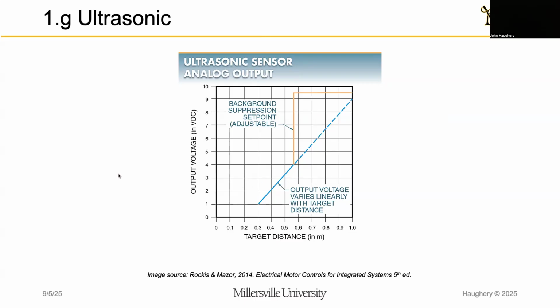So those are applications of solid state sensors. They are designed and implemented around transistor solid state relays. And so the elements that are sensing the physical phenomena, temperature, flow, pressure, and such, are just energizing or not a transistor that has a contact on the output that is either open or closed. That's an oversimplification, but that's the comparison to a mechanical relay that will make sense with the other things that we've gone through in this class.